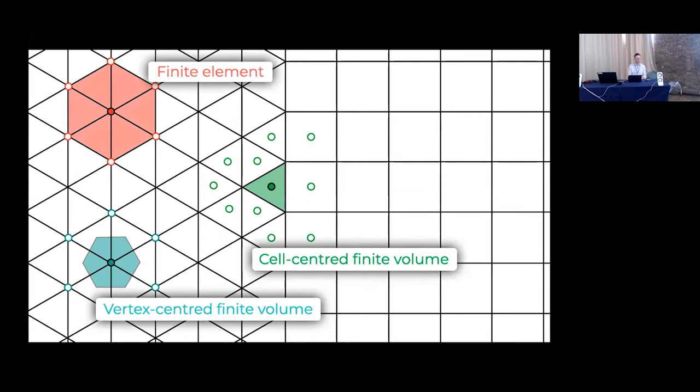For comparison, finite element methods will enforce that equation on all the elements around a node. So not just split, they don't define a second mesh, they define it over all of those elements. So for that center node, they will enforce it over the volume of all of that red area in some weighted way. In contrast, the finite volume method enforces it just over the boundary, divergence terms over the boundary of its volumes. So that's not philosophical, that's an actual difference between the two methods.